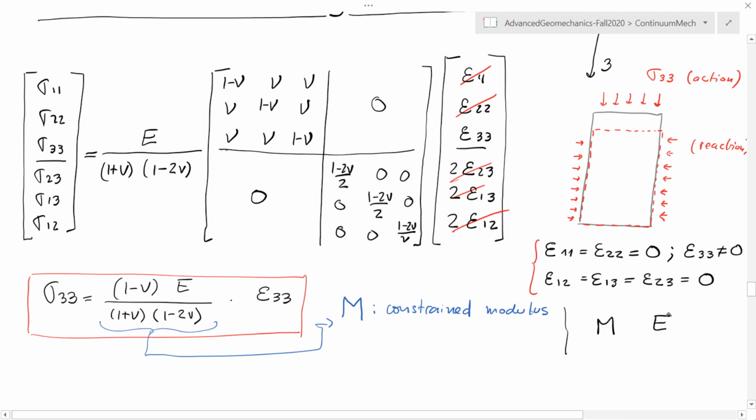Well, in order to solve that, let's try to look at this example. As long as the Poisson ratio is higher than 0, you could imagine that if you were to compress this solid and achieve a given strain, let's say 1%, it's going to be harder to do that if you have the sides which are not able to expand or to relax that stress I am applying, than if I had that boundary condition holding the solid to the sides.